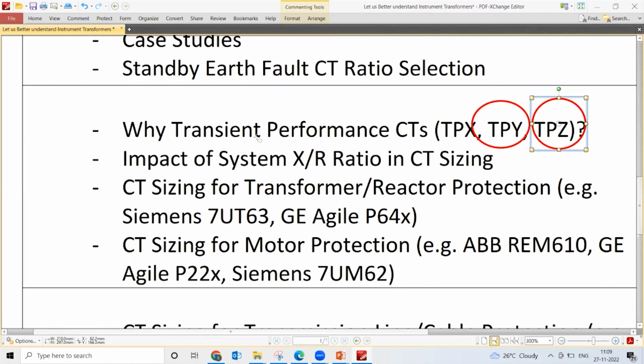and transient performance is extremely important. It's not just measuring the RMS current, measuring the actual current is also important, because faults are determined or identified using fast Fourier transform algorithms in the sophisticated relays, in even less than 3 or 5 milliseconds nowadays. Your overcurrent relays or earth fault relays may take 1 cycle or 2 cycles, 20 milliseconds or 40 milliseconds to detect whether it is a fault or not.